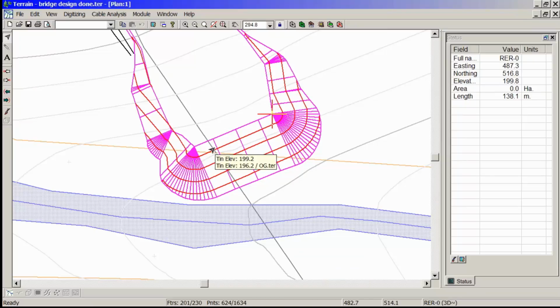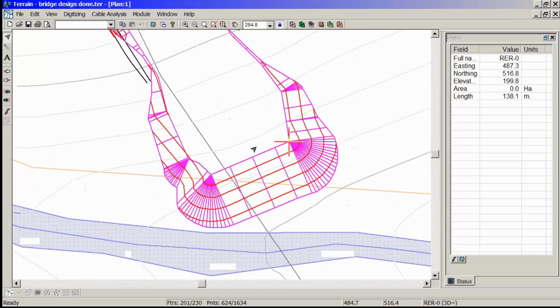Okay, so what I've done so far is I've exported break line features from the location design module as a terrain, joined a couple of features together, making a closed boundary, graded down to the ground, manipulated those features, and redrew them so that I can make a turnaround at the end before it crosses the bridge.